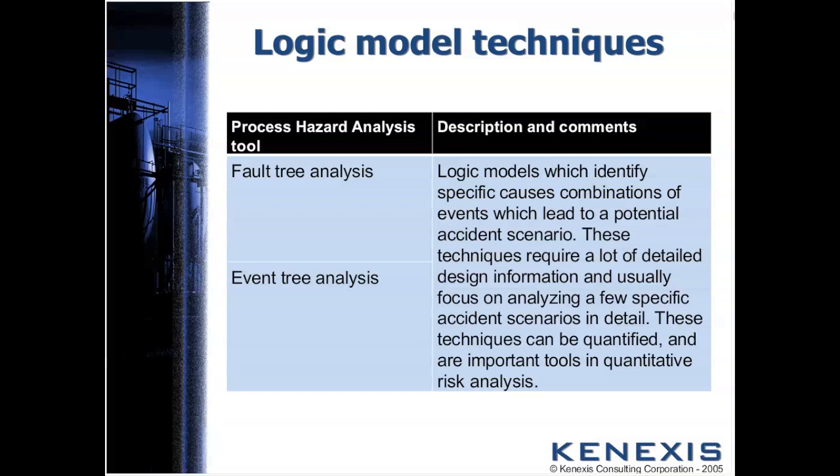The purpose of a fault propagation model is to estimate the failure characteristics of a system based on the individual components of the system and how they're logically related to each other. Of the fault propagation models that are commonly out there, fault trees are particularly useful for analyzing failure frequencies of process plant systems due to their flexibility, accuracy, and incredibly good documentation characteristics.